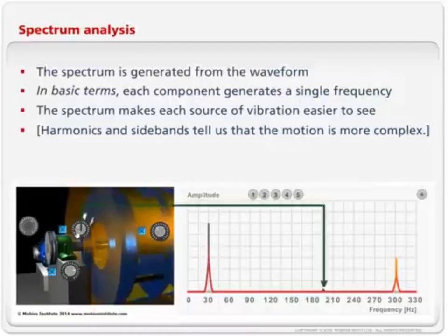If my original vibration looked like that, and there's no bearing vibration, and the next time there was more, and then more, I'd start to become concerned that the bearings were going to fail. And now, with that early warning, I can go and start the planning process to replace that bearing so that it can be ordered, so rather than us having to keep it in our own spares inventory, we can order it from the vendor, have it here in plenty of time, plan the job, kit the job, find the right people and tools and all those other things that we want to do.